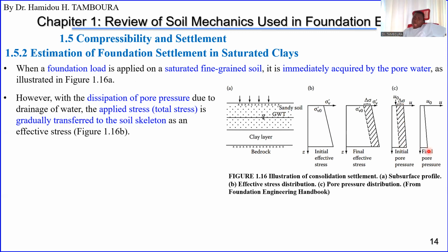And at the end, the final pore water pressure will be like this small one, okay? And it is here. So it means all this part, when the water drains, this part of the stress will be transferred to the soil skeleton. Here is when we have equilibrium of the pore water pressure. When we reach equilibrium of pore water pressure, the profile will be like this. And initially it was like this.